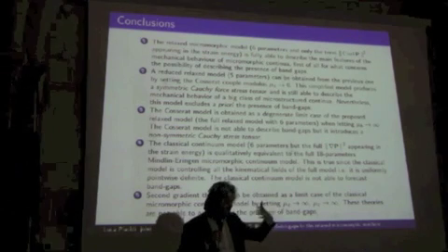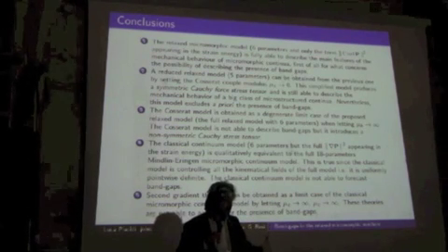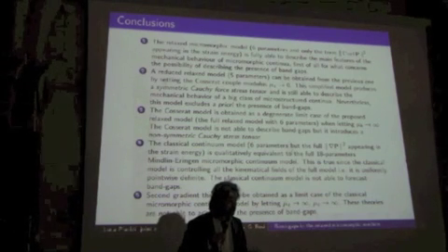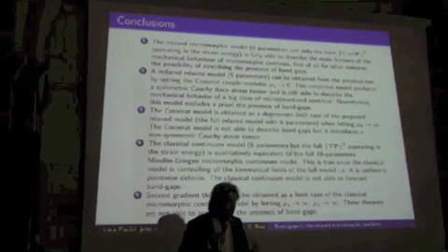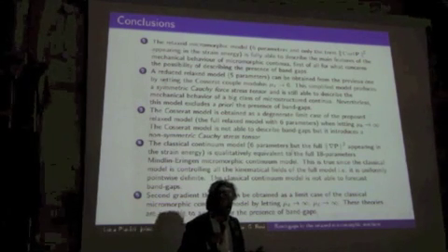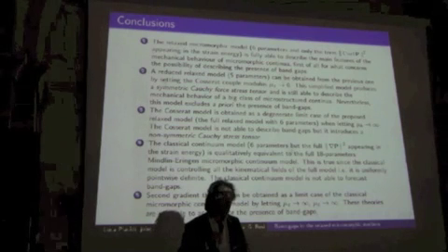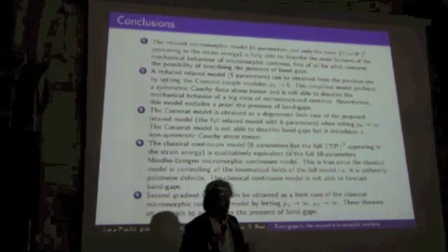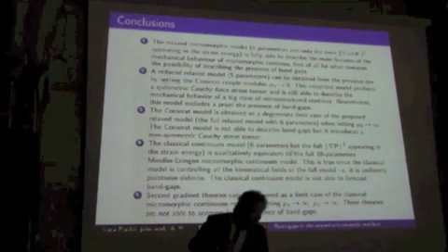Then from this model one can reduce one parameter and arrive at a 5 parameters model with mu c equal to 0. This simplified model produces an asymmetric Cauchy force stress tensor that is sometimes useful, but this model is not able to see band gaps.